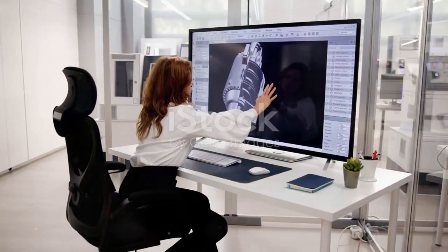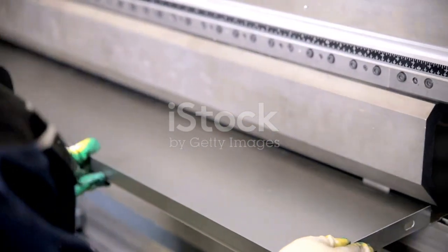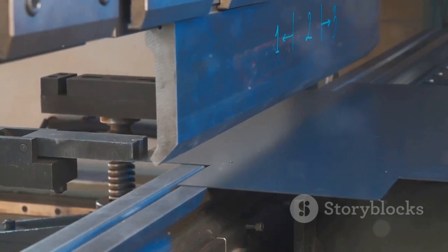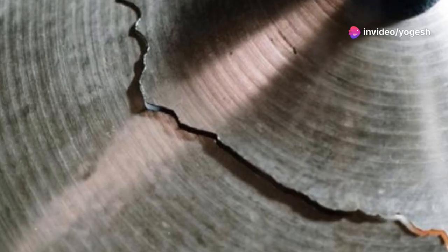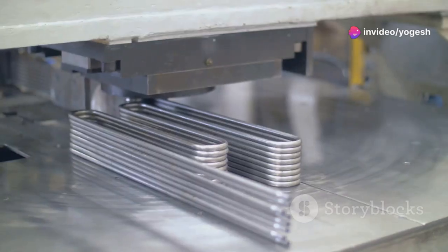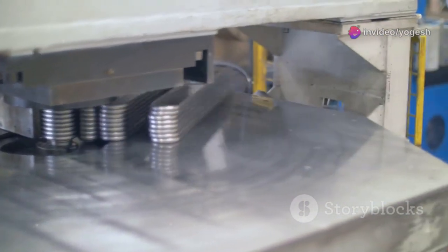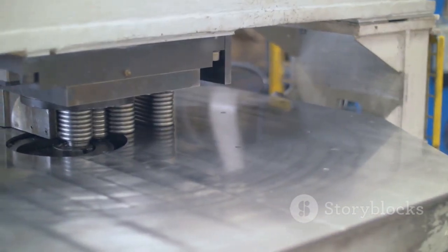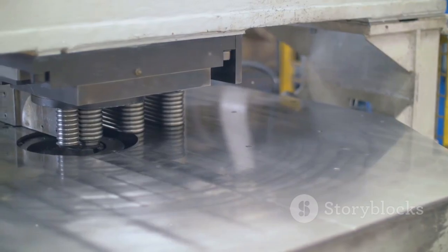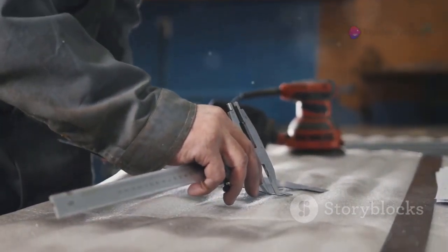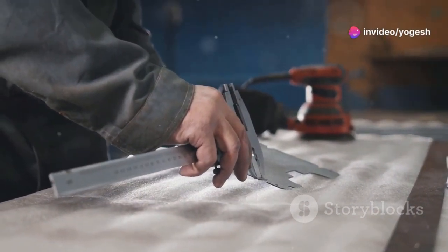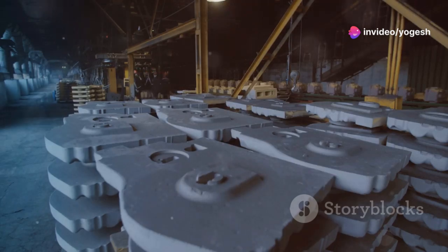Rule 1. Always respect the minimum bend radius. Bending metal compresses the inside and stretches the outside. A sharp corner will crack. Every bend needs an inside radius, typically at least equal to the sheet thickness for common materials. For a 2 mm thick aluminum sheet, use a 2 mm inside bend radius. Cracked bends mean failed parts and wasted resources.